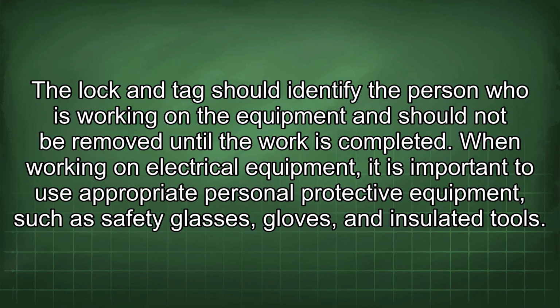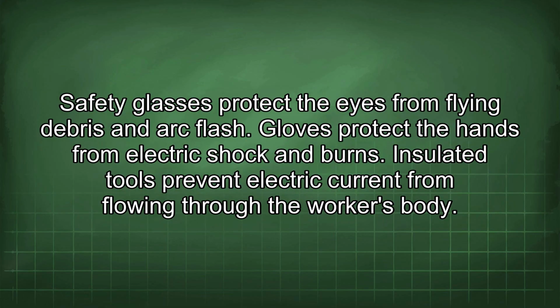When working on electrical equipment, it is important to use appropriate personal protective equipment, such as safety glasses, gloves, and insulated tools. Safety glasses protect the eyes from flying debris and arc flash. Gloves protect the hands from electric shock and burns. Insulated tools prevent electric current from flowing through the worker's body.